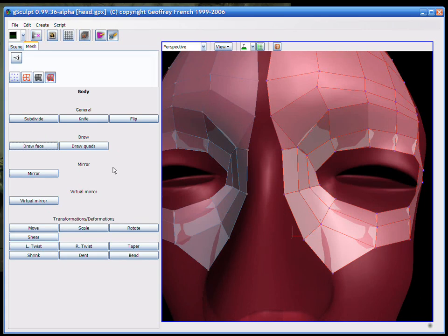Often you will find that if you draw the face in an anti-clockwise direction, it'll appear to be front-facing, it'll appear white. If you draw it in a clockwise direction, it'll appear black because it'll be a back face. If you use existing vertices, however, it'll automatically flip it such that its direction will match with the surrounding faces.